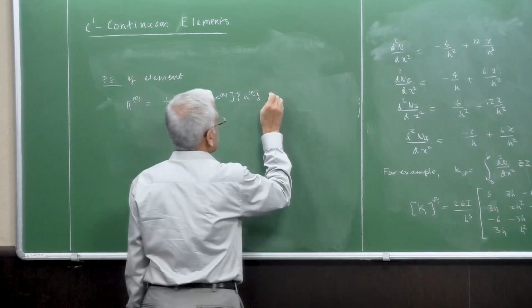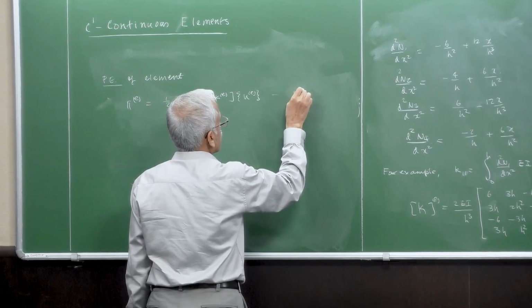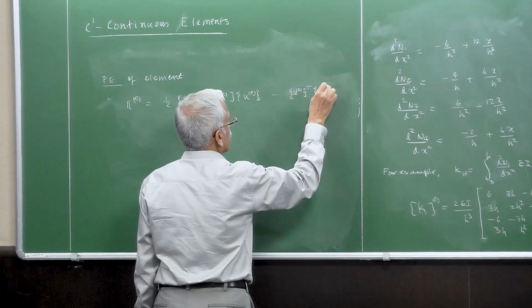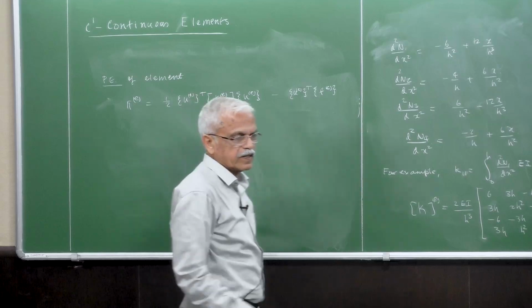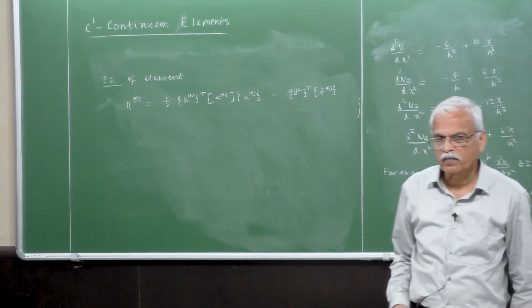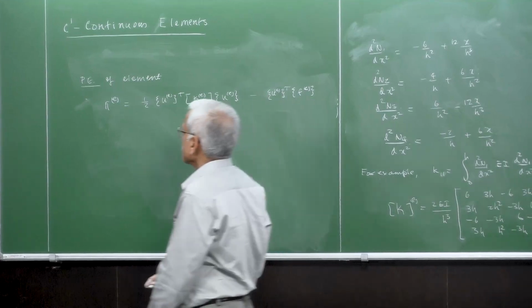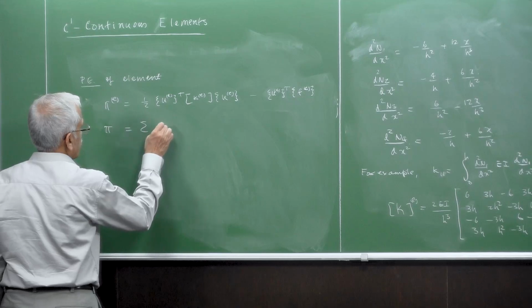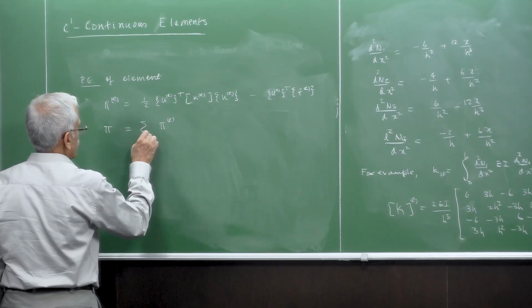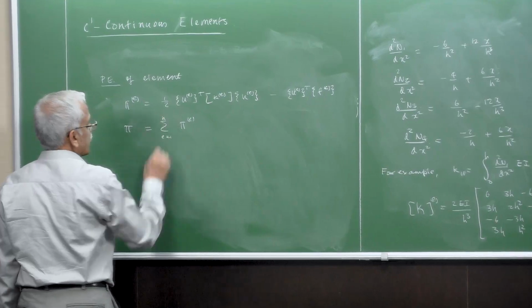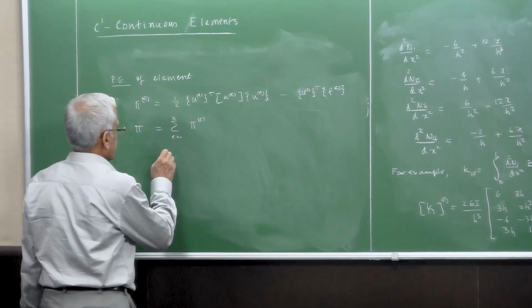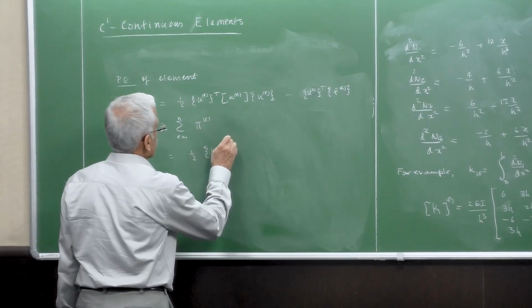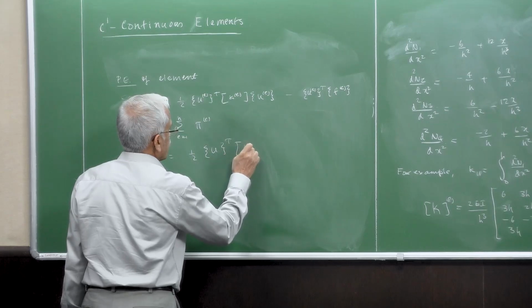This procedure is quite similar to our earlier potential energy formulations of the solid mechanics. So it is the same thing. So this is for one element, and if you go over all the elements, okay, this can be written as the usual, K global.